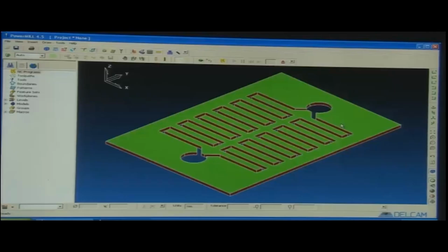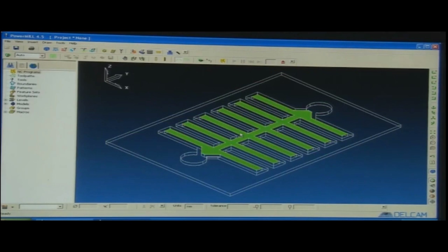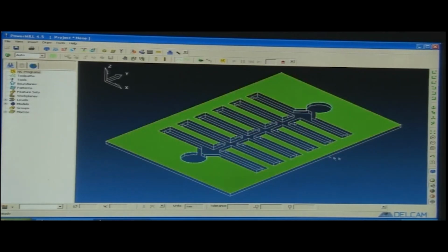So, basically a machine should have 3 axes. What we will use is a 3-axis machine on which we will manufacture this component that we are showing here. So, this is the component. We can write the code for each and every corner, like this corner or any profile. We can write the code for each and every point here. Manually, the code can be written, it is known as MDI, manual data input. Then there are a number of faces here, you can see there is one face, another face. We can write the codes separately.